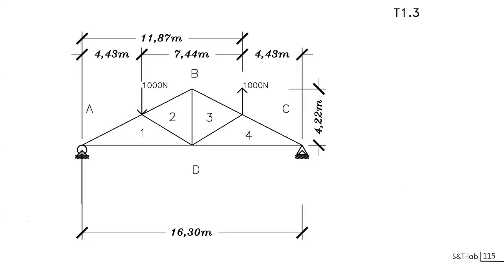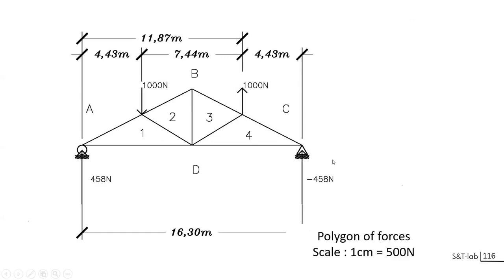This is the kind of system you have on a framework, pushing with 2 bars here. And you have to assess first what would be the reaction forces. So using the principle of the equilibrium of bending forces, you will be able to get the resultant of forces as applied here. So you put the bar somewhere here, you make the equilibrium around this. You have this force acting with one lever arm, a second force here acting with a second lever arm, and a third reaction acting with a third lever arm from here to here, and you get the value here. What about solving the system?